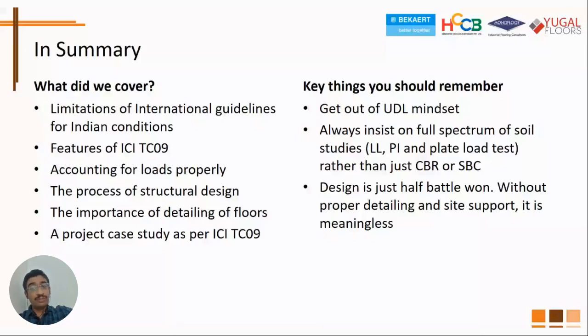Also insist on a full spectrum of soil studies, because you heard Piyush talk about liquid limit, plasticity index, plate load test. These are some of the things we find missing in our soil reports, honestly. And rather than just basing our reports on CBR value or SBC, which is not the right parameter, mind you, for grade slab design. For foundations and other things SBC may be fine, but not for grade slabs. And the design is only half the battle won without proper detailing and site support. All of this is meaningless otherwise.